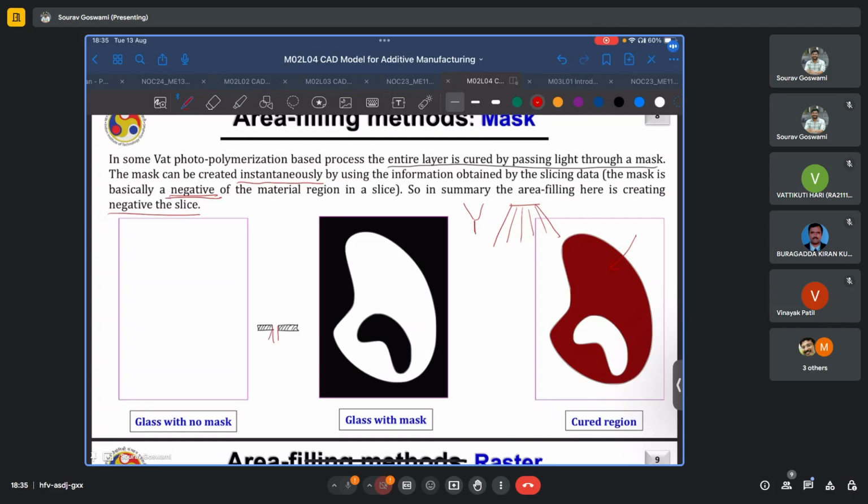Often you will have diffraction of light, and thus on your actual photoresist, the illuminated surface will not be just the sharp shadow of the light, but it will actually be diffuse. This was your desired region, whereas in reality this entire region is getting illuminated. Thus, we should design our masks and optimize the distance between the mask and the illuminated layer to minimize such diffraction effects.